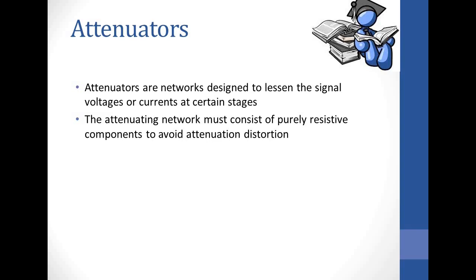If you recall from electricity, capacitors easily allow high frequencies to pass, whilst for low frequencies they introduce a very high capacitive reactance, and vice versa for inductors. Inductors easily allow low frequencies to pass, whereas for high frequencies they have a very high inductive reactance, therefore blocking high frequencies and allowing low frequencies to pass. But for resistors, all frequencies are treated the same way. The resistance doesn't change with changes in frequency.